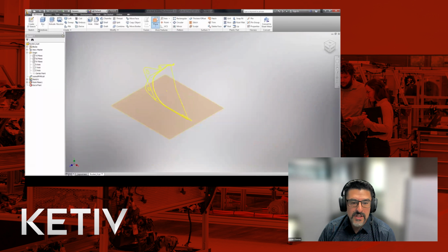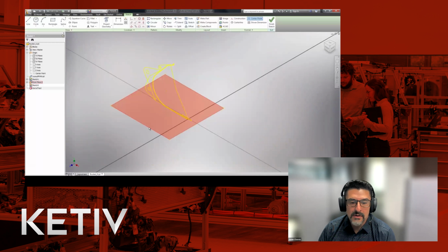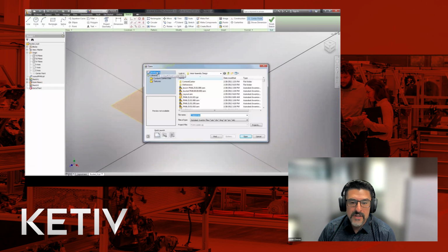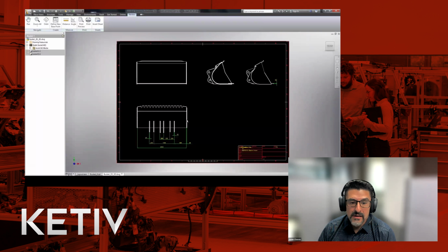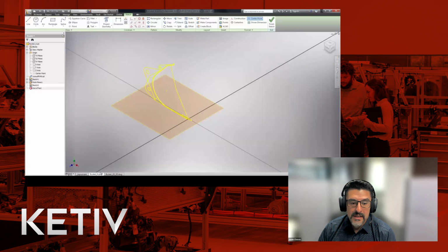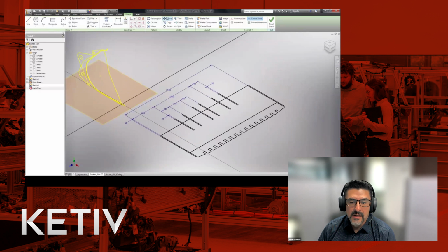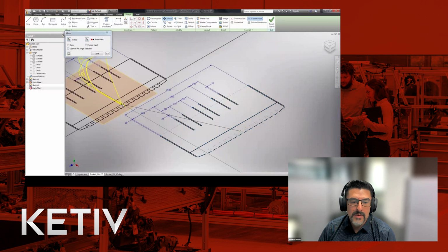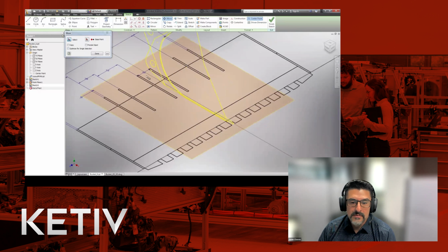So there's already one sketch there that was copied and pasted from AutoCAD. We're creating a brand new sketch. We're opening up AutoCAD directly from Inventor. And when you do that, you can just copy and paste directly. So as we paste it in onto this other plane, it's going to be in the wrong position, and we're going to go ahead and just move it so that, in relationship to each other, there's a common datum point that they both share.